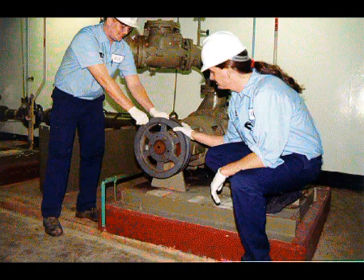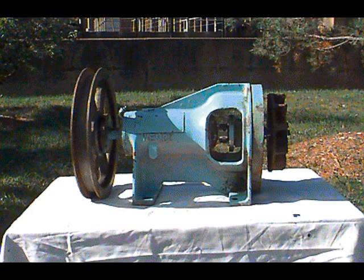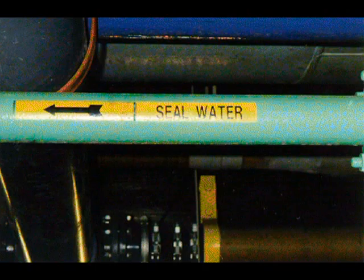If a pump with a mechanical seal is not being used, it is good to rotate the shaft slightly every day to avoid setting of the two faces. Refer to manufacturer's literature for specific information about maintenance, inspection, and replacement of these seals. Regular checks for vibration, noise, temperature increases, and leakage are required. When a mechanical seal requires replacement, either call in a mechanic, or if qualified personnel are available to change the seal, follow manufacturer's instructions.